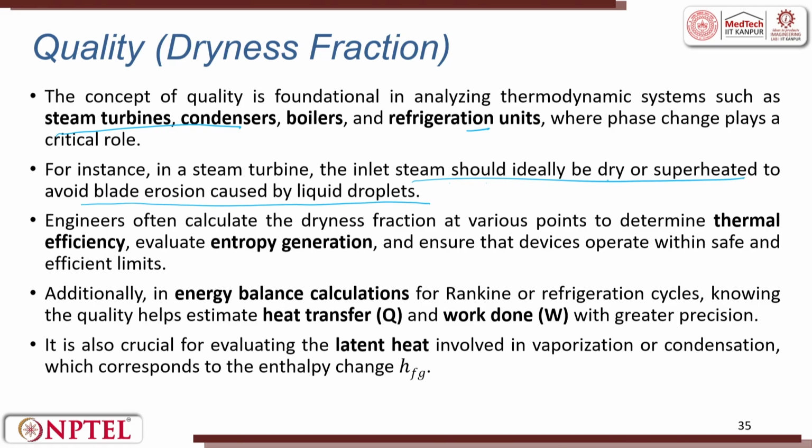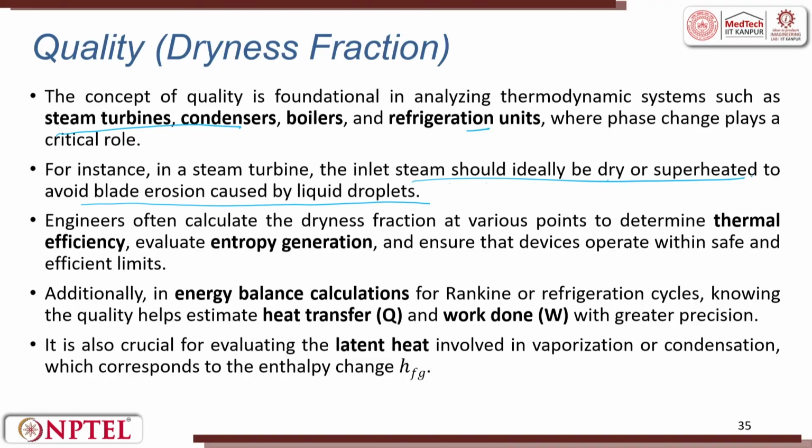Because it is completely vapor, it is going to be easy, because the vapor hitting on the turbine blade will start rotating. If there is a molecule of water along with the vapor at very high pressures, then what happens? This becomes like a small bullet trying to hit the blade. The blades have a profile, so it is very difficult to manufacture blades. So, they always try to have dry or superheated steam going inside.